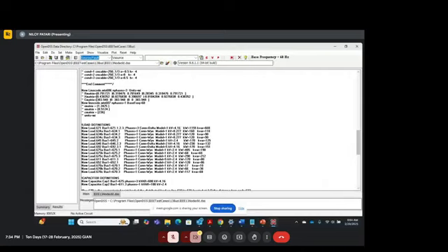Load definitions means you define certain loads. Suppose I define a new load which is 671. It is connected to bus 1, means it is connected to this bus which is 671, and it is connected to all the 3 phases, right? So it has dot 1, dot 2, dot 3, means it is connected to all the 3 phases, and it's a delta connected load, and you have the kV, you have kilowatt, you have kVr.